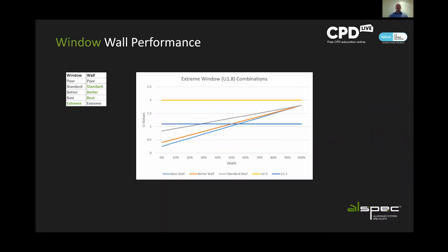And then, of course, if you've got a U value on your windows of 1.8, well, you can use 100% of it in an office building in Sydney because the requirement's only 2. It doesn't matter what you do with your walls; you're always going to be better. Even then, you still need to consider how you design an aged care facility in Melbourne, because the performance requirements are really low, and that's by design. They don't want glass aged care facilities. The National Construction Code has been designed to ensure that we have a practical and usable window to wall ratio.